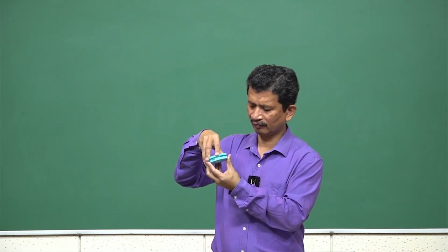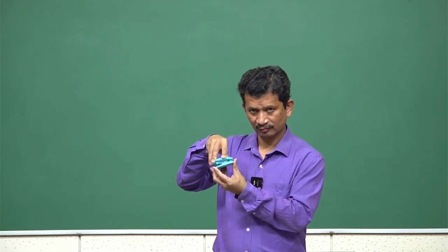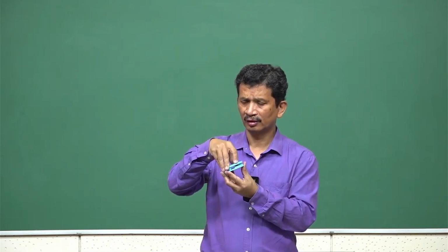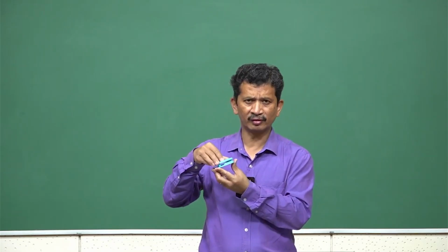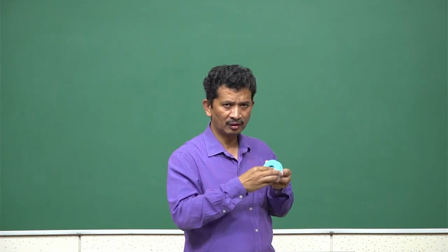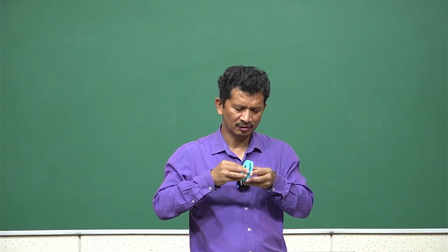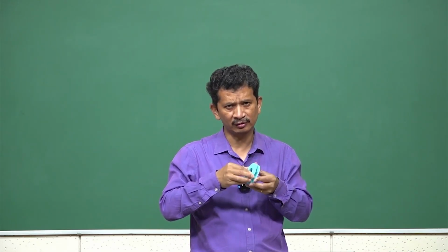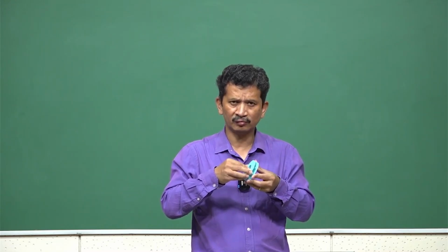So, I can define one axis and it can rotate, and the moment it comes in contact with the flat surface, yes, all 6 are now defined. If I apply enough nesting force and press it and try to move it, I cannot, because it is well defined now, exactly constrained, all 6 providing enough constraints, and I will not have any motion.